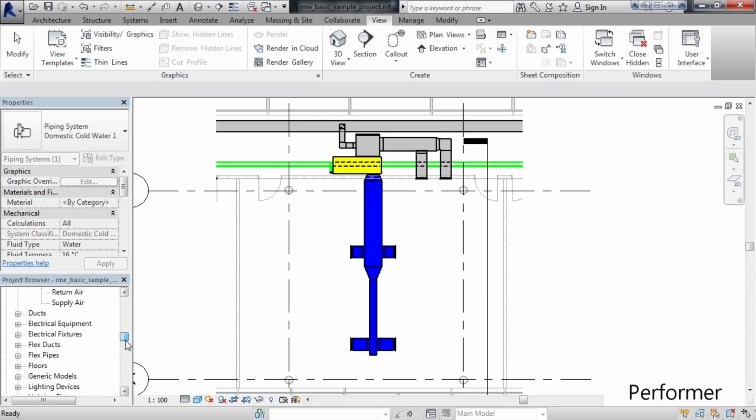Now, if you wanted to make a modification, this gets into where we talk about graphic overrides. Generally, if you want to modify anything here, for example, with this exhaust air system, technically, I would want to duplicate this. Best practice would be duplicate or create a new version of this air exhaust system or this component because you don't want to change any of the original components data because if you go to upgrade, that may be overwritten. So a good practice or good rule would be to create a duplicate or rename it to something else and then change those elements.